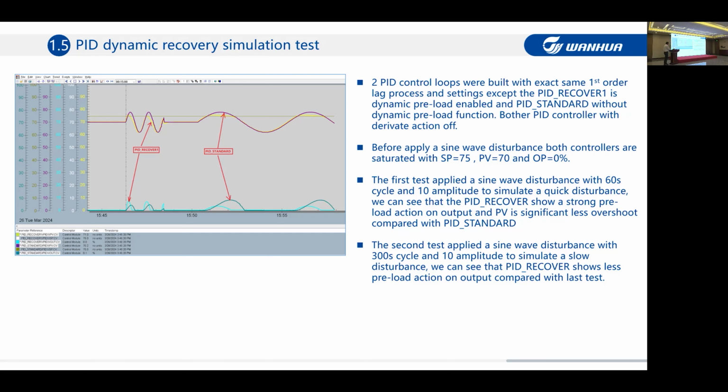First, we applied a sine wave disturbance to both PID controllers, a simulated disturbance with sine wave signals, 60 seconds cycle and 10 amplitude, to simulate a quick disturbance.